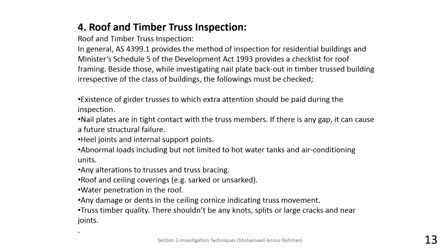Roof and truss inspection. In general, Australian Standard 4399.1 provides the method of inspection for residential buildings, and Minister's Schedule 5 of the Development Act 1993 provides a checklist for roof framing. Beside those, while investigating nail plate backout in timber truss building, irrespective of the class of the building, the following must be checked. Existence of gutter trusses, to which extra attention should be paid during the inspection.